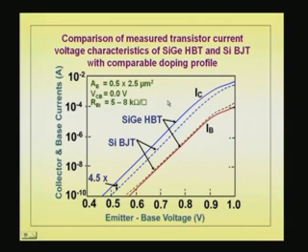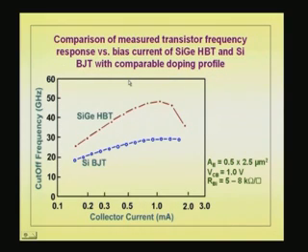As I said right at the beginning, collector current is larger in the case of silicon germanium BJT. There are two curves: collector current in the silicon germanium HBT, and collector current in the case of silicon BJT. So, that is about a factor of 4.5 larger, due to the field and the heterojunction effect, both. Base current is the same, and the device size you can see is 0.5 by 2.5 micron, a very small strip for the emitter. Okay. That reduces all the capacitances which are involved. Then cutoff frequencies: once you get larger current for a smaller voltage, the charging times are all smaller, so you get much higher cutoff frequencies.